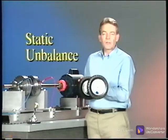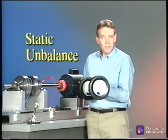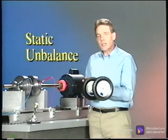This type of unbalance is called static unbalance because it is unbalanced when it's stationary. Static unbalance can usually be corrected in a single plane.